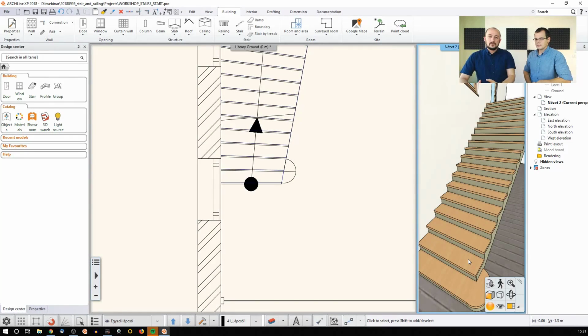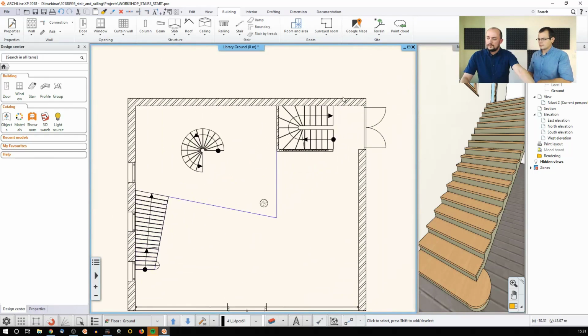You can edit and modify the 2D shape as well. Most of the time, whatever you do, you want to make your changes right away visible in the 2D and be reflected in the 3D. But there are specific scenarios when you would like to edit the 2D shape of the staircase without modifying the stair itself. And this situation, I think it's better described with another shape, which is the first one that we